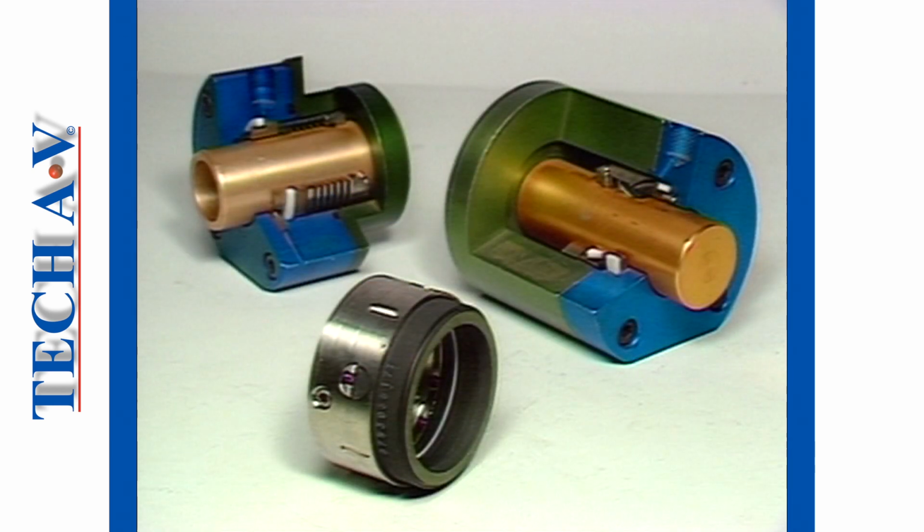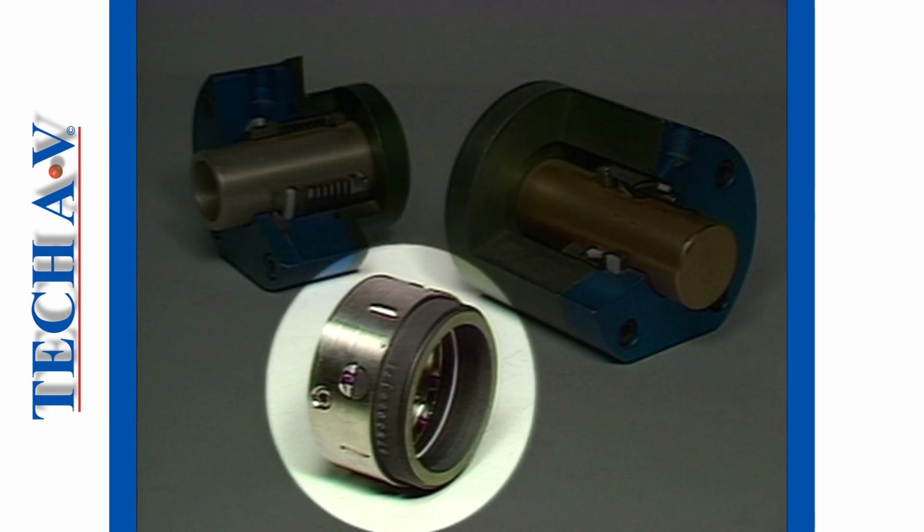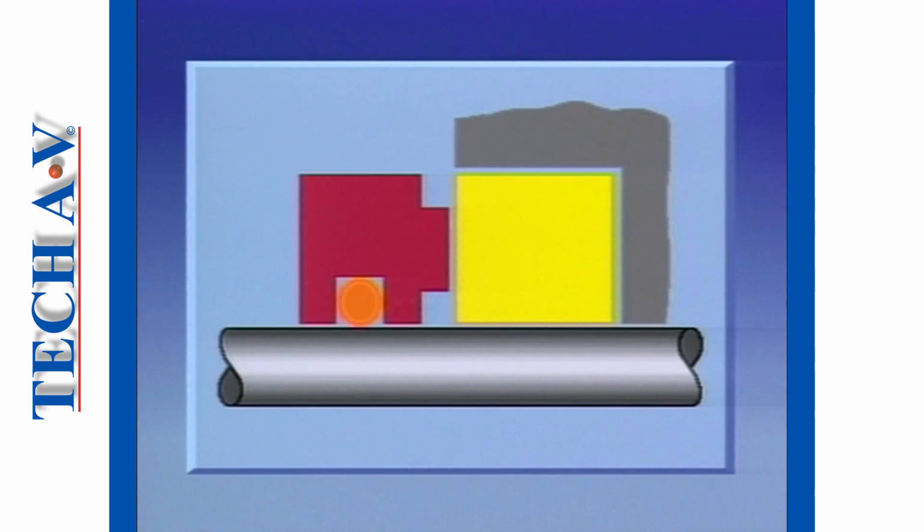However, let's overview the principles of a typical secondary seal, such as the O-ring type. Here, an O-ring is situated into an annular groove, usually cut into the primary seal. As hydraulic pressure occurs behind the O-ring, the rubber is forced to deform into the leak path, thus effecting a seal. When the pressure is released, the O-ring will revert back to its original shape.